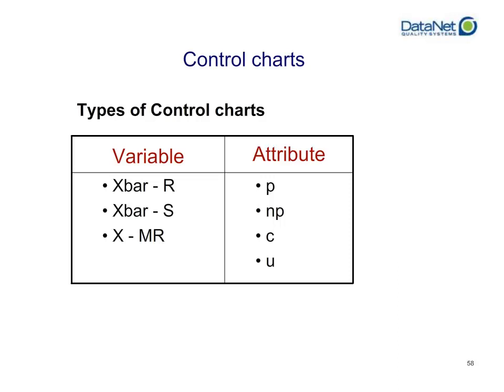We will cover what each one of those charts is as we go through the slides. But just a quick overview of the most common one, the Xbar and R: the Xbar is the average value of your samples within a subgroup plotted onto the control chart, and the R is the range, the largest minus the smallest value within that subgroup, plotted onto a control chart.